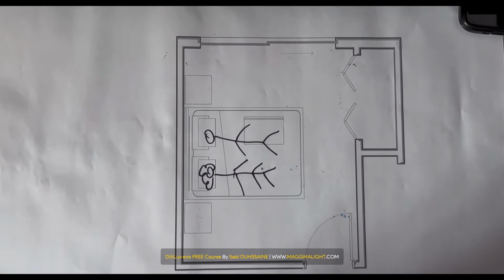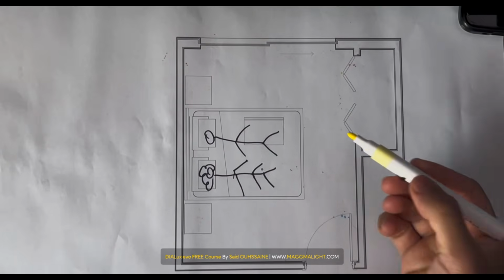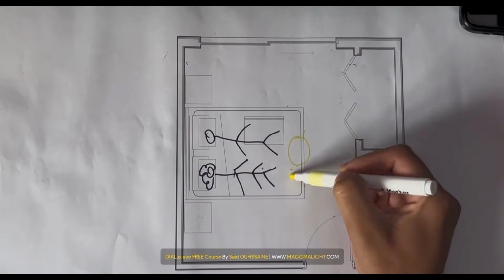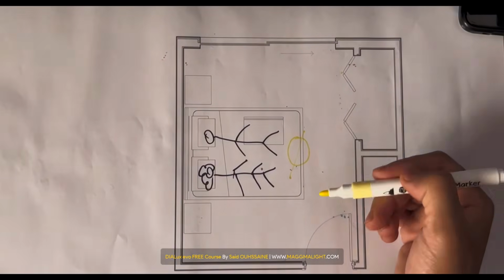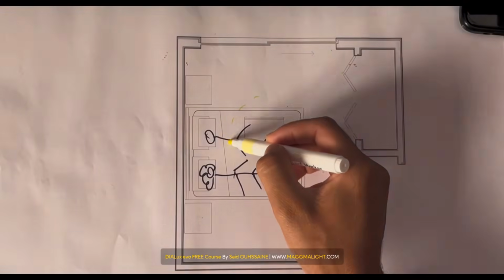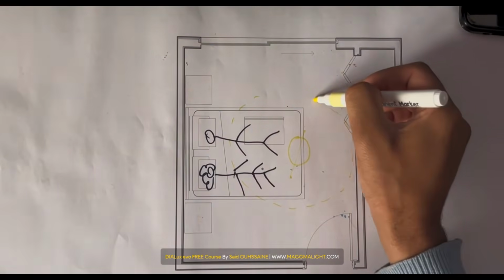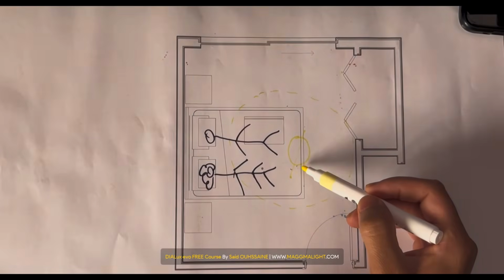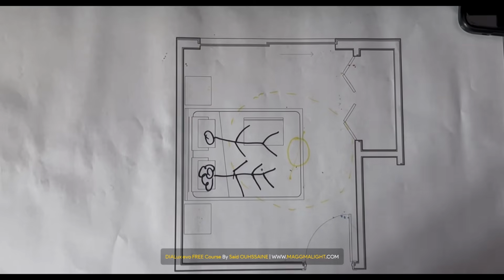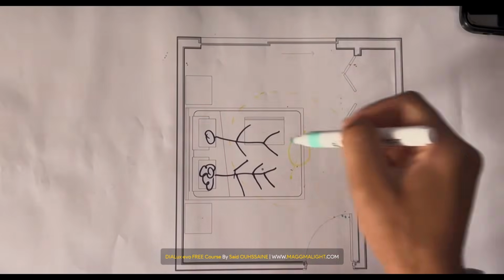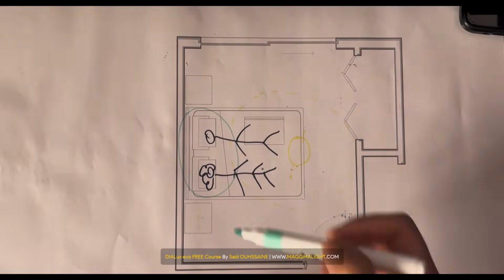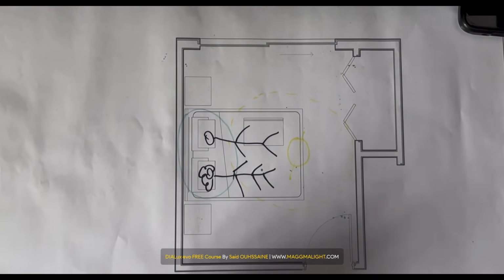Let's start with the first layer, which is the general lighting. I would place a luminaire that's going to be a suspension in this case because I have enough height actually, and this suspension I would need it to provide me lighting in a circle like this, so the beam angle should not be very small or very wide because I actually don't want the direct light to get to this part of the bed to glare the lying couple.